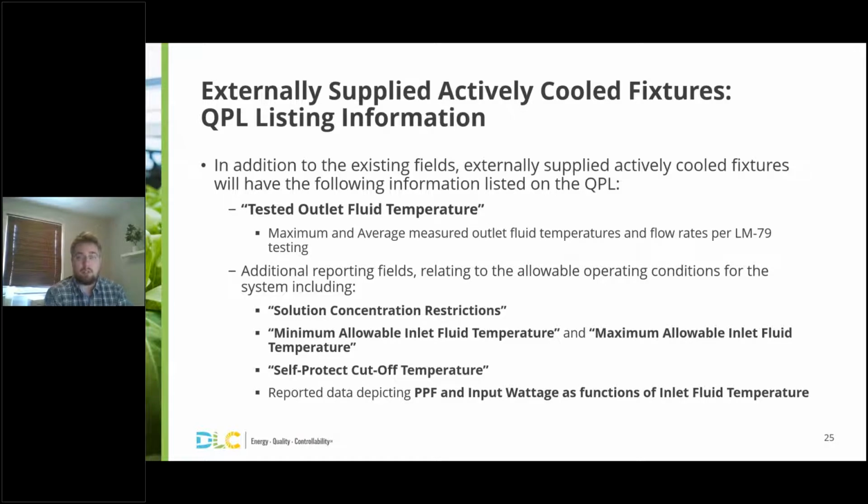So not just for qualification, but for stakeholder information, as well as the minimum and maximum allowable inlet fluid temperatures, which are defined by the manufacturer's allowable range. That'll be reported in the QPL. The self-protect cutoff temperature will be reported on the QPL, as well as the data that depicts the PPF and input wattage as functions of the inlet fluid temperature.